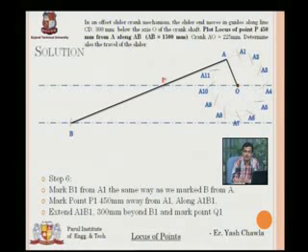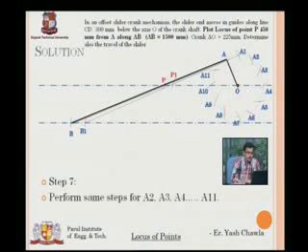Now with radius equal to the connecting rod, that is AB, I'll put my pointed end at A and cut an arc at B1. Connect A1 B1, then mark point P1. How did I mark point P1? I'll take distance equal to AP on my compass, put my pointed end at A and mark my point P1. Now again the same thing I'll repeat for A2, A3 till A11. I'll mark B1, B2, then connect A2 to B2, then mark my point P2.